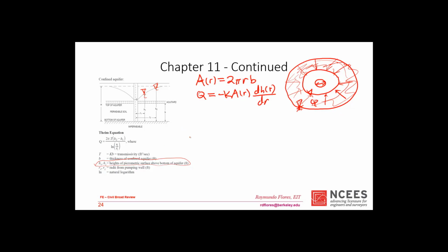Whereas in the other case, your Q region was somewhere between the well boundary and infinity. For all practical purposes it's infinity because it levels off somewhere, we don't know exactly where. But in this case, it's simply this. So that's where this equation comes from. It comes from the fact that you can have boundaries in between, and that would be your limits of integration.